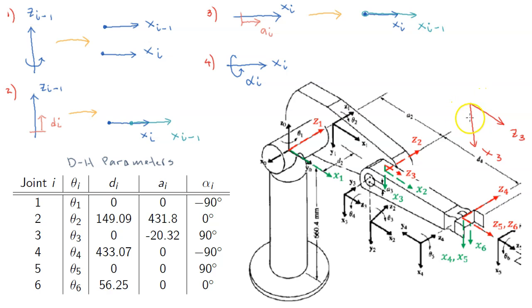So I know my Z2 is down here. So in order to find D3, first I have to rotate coordinate frame 2 about Z2 to make X2 and X3 pointing in the same direction. Okay, so let me use another color. So my Z2 remains here. So I have to rotate this coordinate frame with respect to Z2 to make these two point in the same direction.